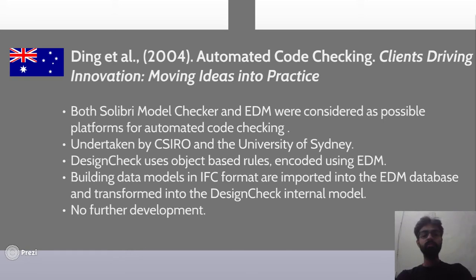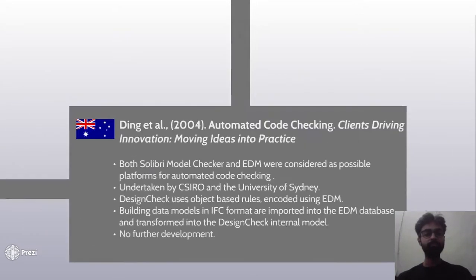Here the design check uses object-based rules encoded using EDM, and the building data models in IFC format are imported into the EDM database and transformed into the design check internal model. And as of now, there is no further development in this project.